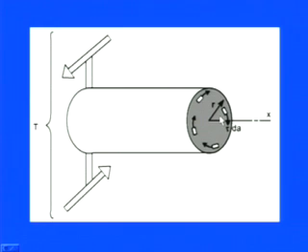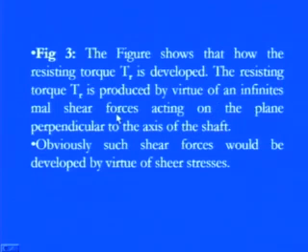We will have a distortion. If I consider that distortion, or the phi which I mentioned in the very first figure, there is an angular displacement. If we consider the angular displacement, and the radius is r, then this tau into dA will give you exactly what the distortion is. That means how distortion takes place in a shaft under the application of this torque. Since we are cutting this section along the x axis, this distortion is there, but if you look along the entire portion, you will find that the layers of the entire portion are equally affected under the application of these torques. So, we need to consider these things.